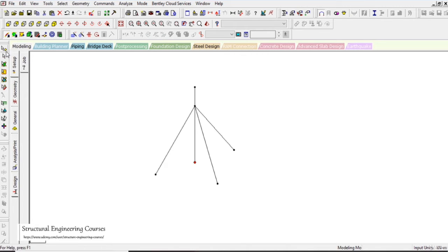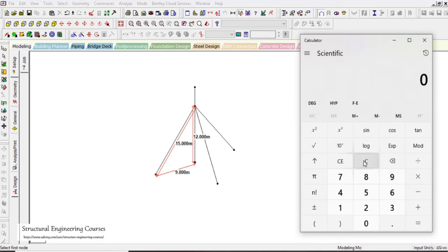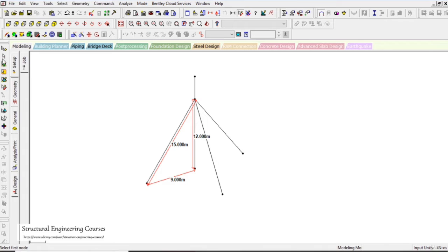So we can model the third cable here, and if we want to see the side elevation, the side view shall be like this. Now this is just the Pythagoras theorem that we are talking about: this is 12 meter and this is 9 meter, so this should be 15 meters. It is nothing but 81 plus 144, which is 225, and 225 is the square of 15. So coming back to our point, this is the simple mass tower and these are the simple guy wires.